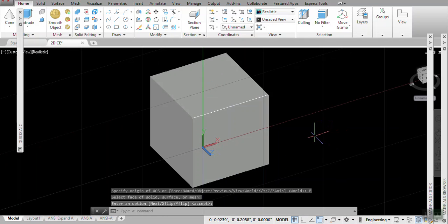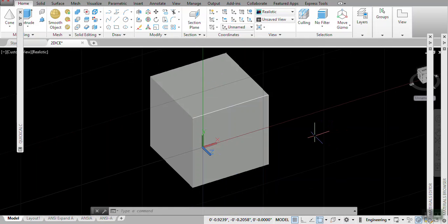So this way, my UCS XY coordinates simply move down to the surface. So I can draw anything I want on the surface. This is a very useful command, UCS, F for face, select the face, click on it, the computer now makes the right surface the current surface. Current surface enables me to draw any line I want.